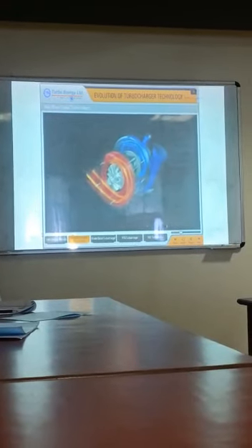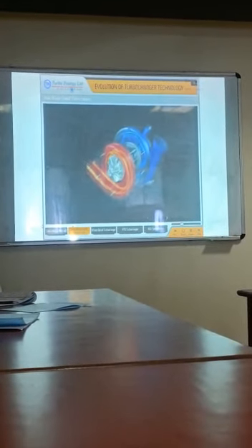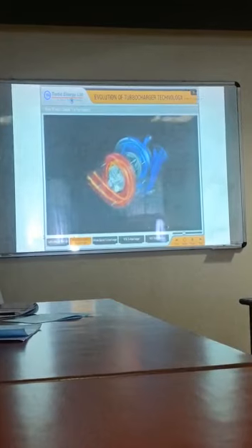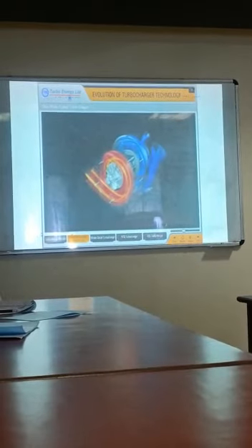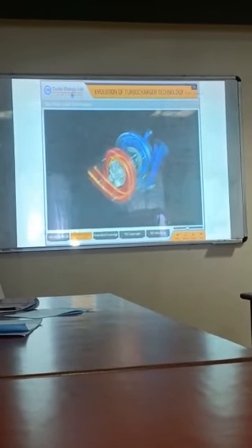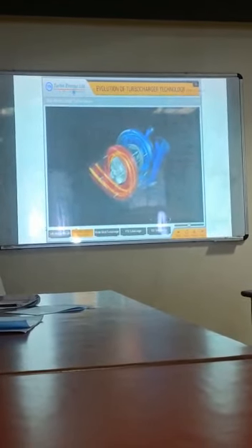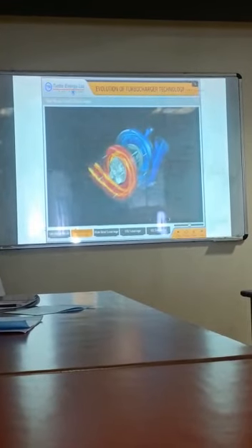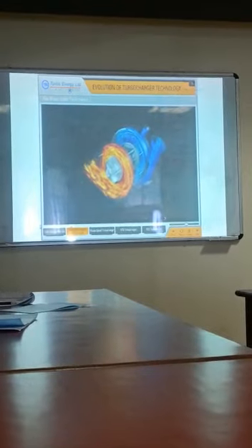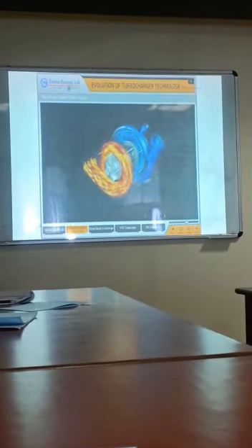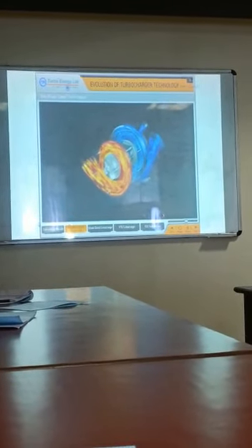As exhaust gas enters the turbine housing, the turbine housing works as a vaneless nozzle, converting pressure energy available in the exhaust gas into high velocity gas. This gas expands over the turbine wheel blades, causing the turbine wheel to rotate. The turbine wheel speed increases with the increasing amount of exhaust gas entering the turbine housing.